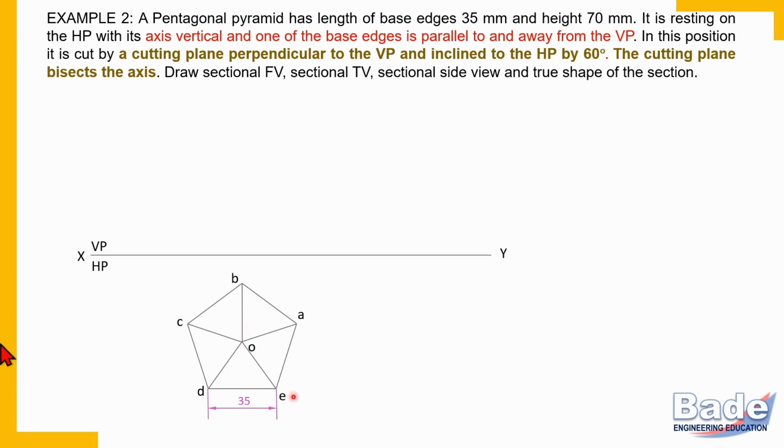in corresponding position. Remember, don't forget to draw any single edge dark. Otherwise, you will face lots of difficulties while completing the drawing. Don't forget to label all corners. Now let's project all these points in the front view. So this is how we have transferred all base corners on the XY line. Label all these points. So A dash, E dash, B dash, D dash and C dash.